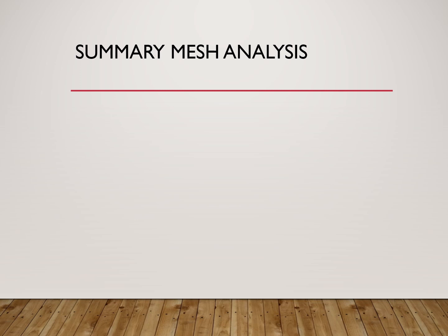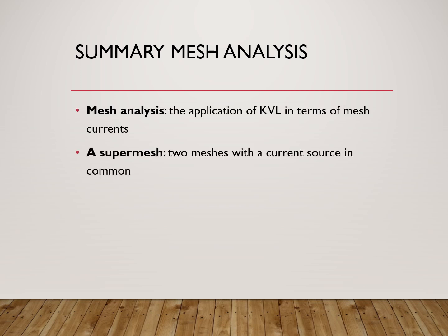Okay, so summary. We have discussed mesh analysis and super mesh analysis in this video. Mesh analysis and super mesh analysis both apply KVL. In super mesh, there is a current source which is common to two meshes, and at the same time super mesh analysis involves a KVL and a KCL equation.